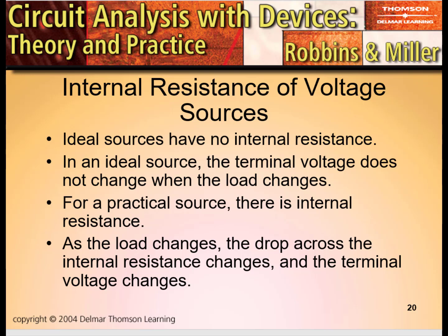And then the person driving the vehicle starts the vehicle. What do you notice about the headlights? They dim while the motor's being cranked over and being started. And that's really because the cranking of the motor is the highest current load in all of that vehicle.